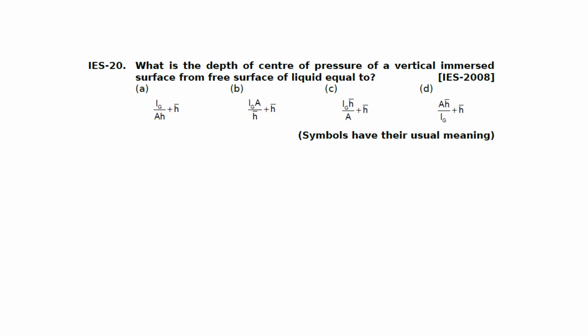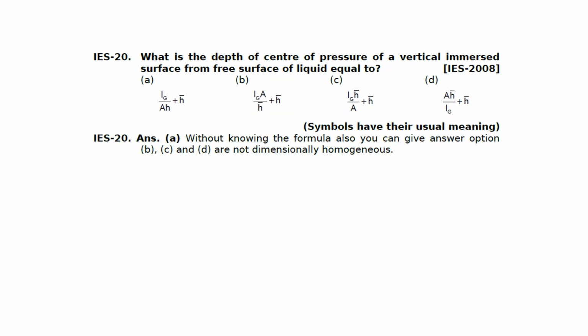Next question, a similar kind of question repeating. What is the depth of the center of pressure of a vertically immersed surface from the free surface of liquid equal to? These are the options. I think you can easily answer the question. It is actually A, IG by A h bar plus h bar.